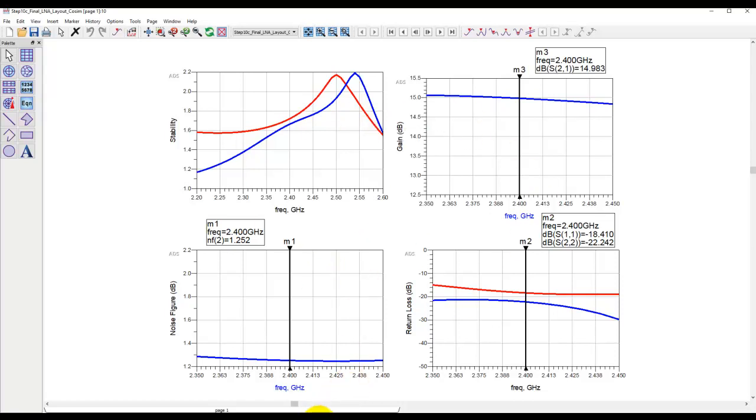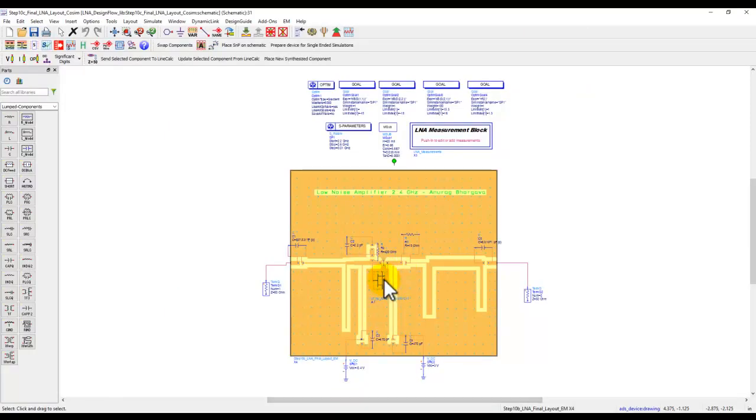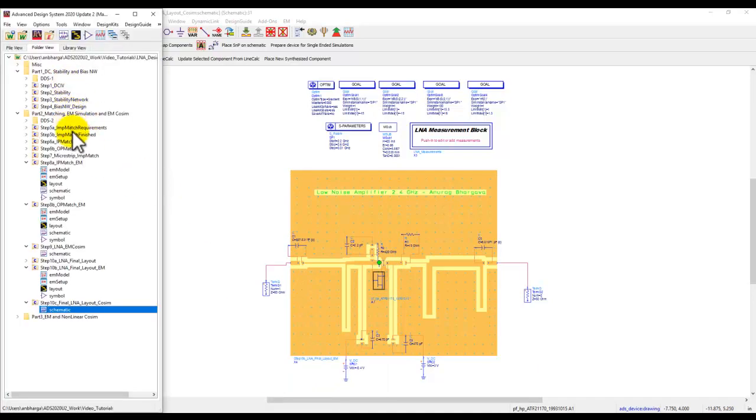Now, if you were working with an S-parameter model and you didn't have this nonlinear model, there is no change for any of the steps which I mentioned here, except you can't do step number 1. But apart from step number 1, the only difference is that I'm using this FET, you would be using an SNP, that's it. The rest of the process is exactly the same.